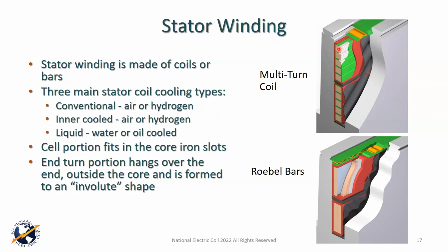If we've got enough voltage inside the strand insulation, we'll just use the strand insulation for both the strand, addressing the strand voltage as well as the turn voltage. Well, looks nice on paper, but one of the things that you're going to realize over time is that coils in the manufacturing process, coils during the winding process, and coils during operation, they see a lot of mechanical stresses. All right, let me say that again.